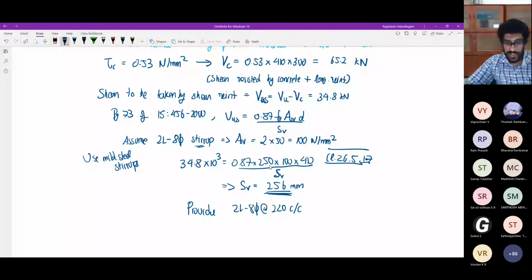So it's a bit of a waste. I can still give the same 500 fy bar at 220 center to center, but I need not give it. So that's why I resorted to mild steel bars. However, the main longitudinal bars are still 500 fy.